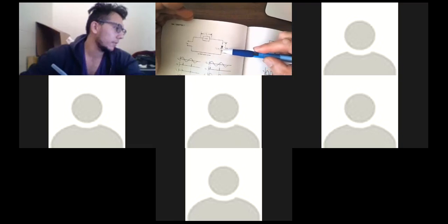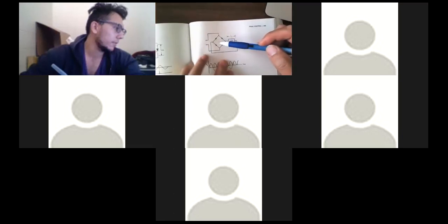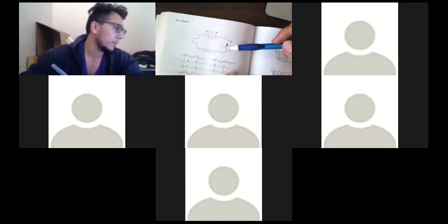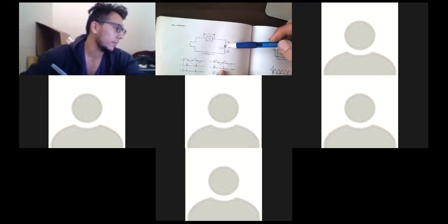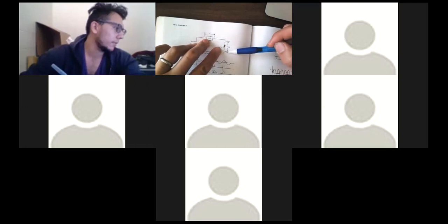Conventional diodes do not have control. So this is an uncontrolled diode right here. That's a diode, but there is no control. It's an unconditional one direction flow. So if you have a flow in that direction, it's unconditional. This diode, SCR, is conditional. So even though you have a right direction flow, it's only able to flow if the control is active.